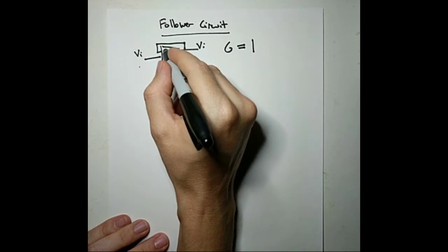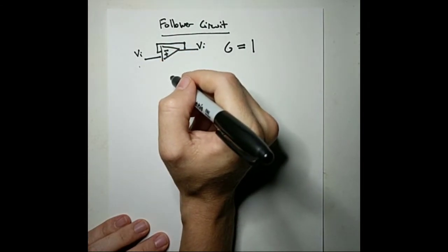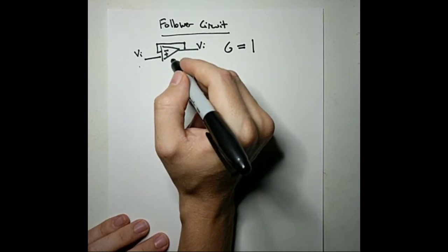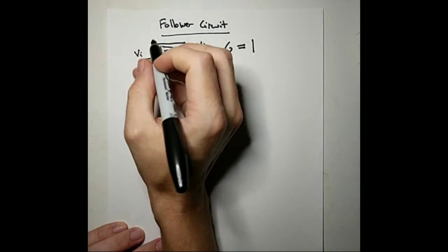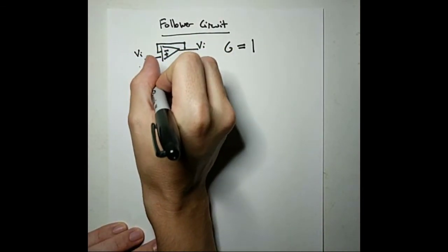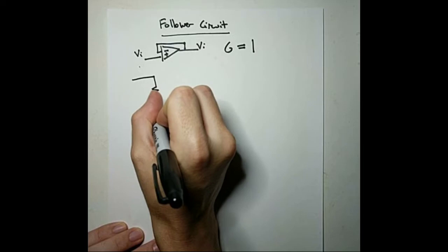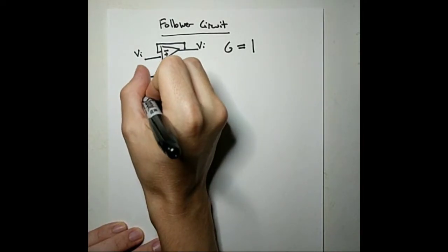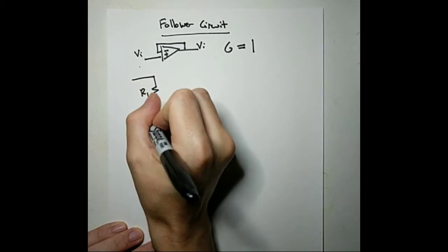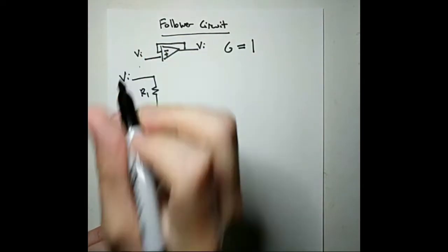But because no current flows through here, and ideally you have an infinite resistance, we can use this to get the voltage out of a voltage divider without loading the circuit. So for example, we had our basic voltage divider like we looked at last week.